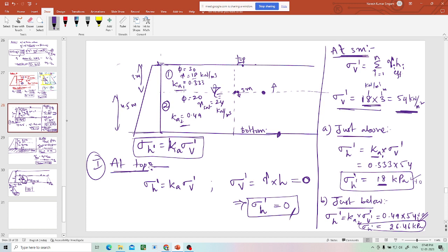Coming to the earth pressure, you have to use total pressures because it's a wall. At the end, the wall is subjected to this total pressure, which comes from the soil as well as water. But when we talk about vertical stresses, they are between the soil particles.